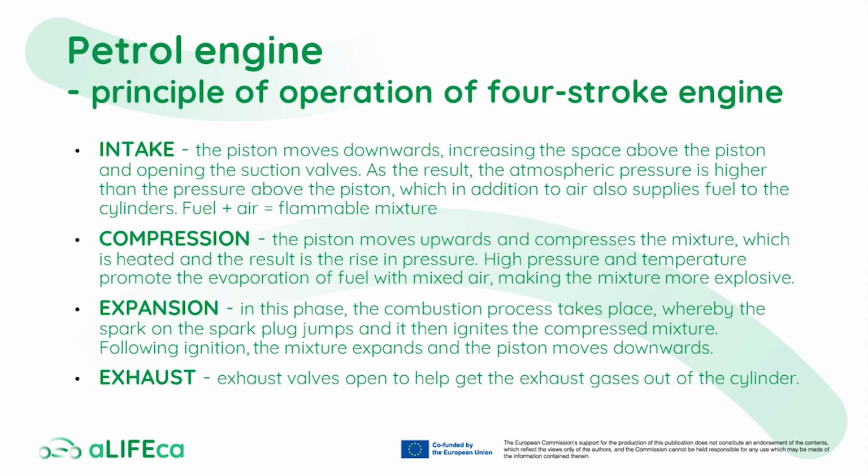First stroke is intake. In this stroke, the piston moves downwards, increasing the space above the piston and opening the suction valves. Second stroke is compression. In this stroke, the piston moves upwards and compresses the mixture, which is heated, and the result is increased pressure.